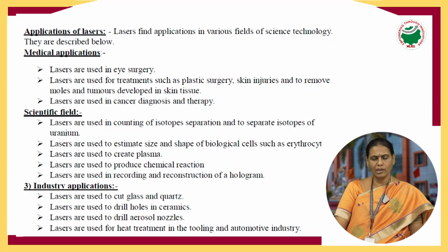They are used to drill aerosol nozzles. Very different peculiar thickness nozzles will be there. So to drill a hole, this laser light will be utilized. They are used for the heat treatment in tooling and automotive industry. Now you want to cut anything, you will heat this by using laser light. You will heat that material and then you can use it for cutting.